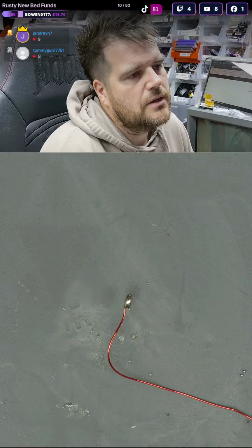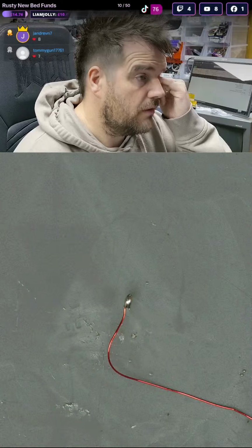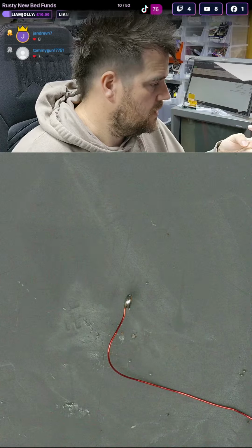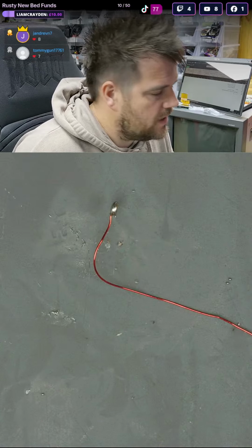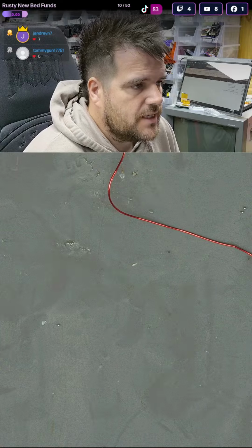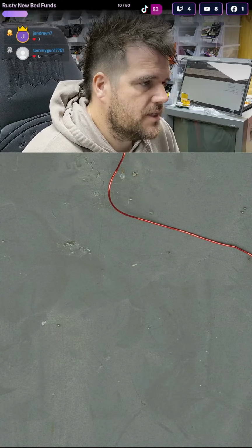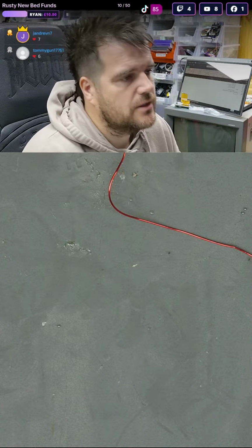I've got a red light boot but no sound. Yeah, so ignore the screen completely then if you've got no sound but you've got red light boot. Go to the wiki and go to reading game cart. You need to check if you're comfortable reflowing the A6. I'd reflow the A6 just to be safe. Reflow the Z80. If you don't want to do them, then you don't need to, but that's the first recommendation.